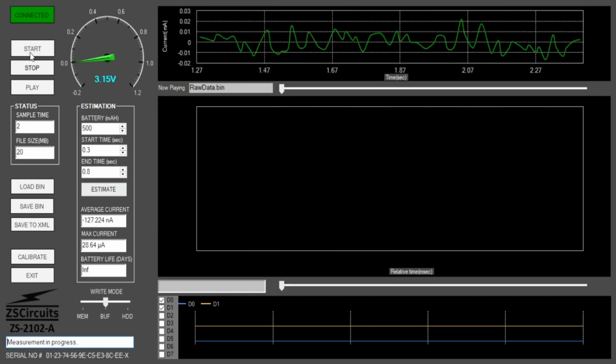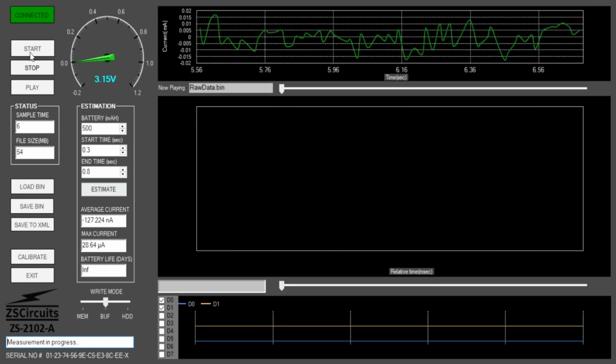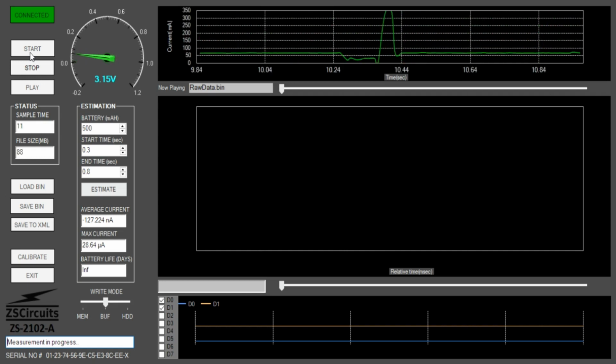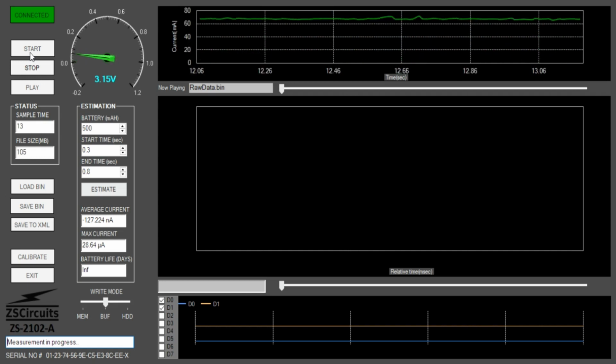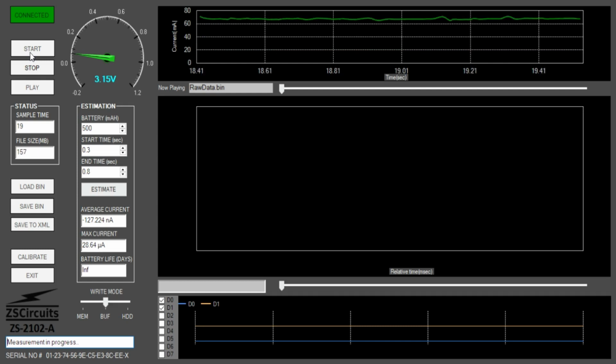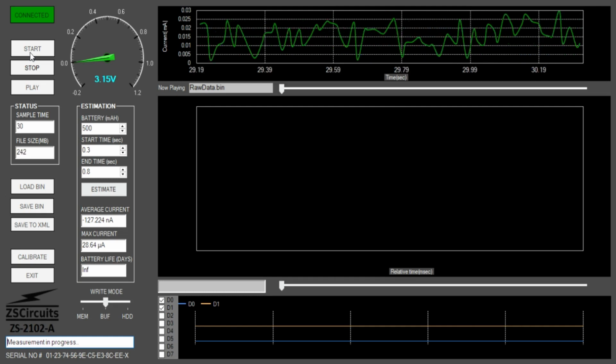The Wi-Fi module is not yet connected to the power profiler. We connect the load now and we see some spikes immediately as it draws current. We notice several transmissions from the module as it connects to an access point. After some time it enters the sleep state. The module is now in the sleep state where it draws few microamps. We will measure this accurately at a later time.